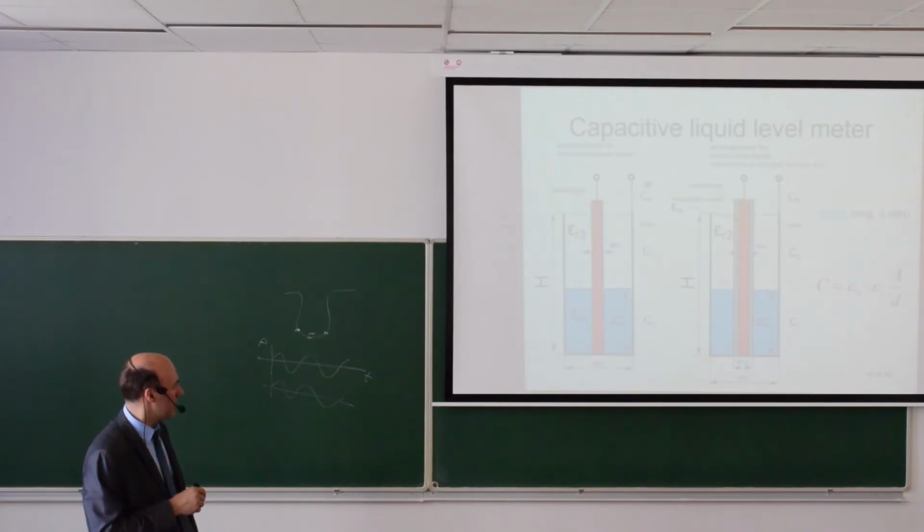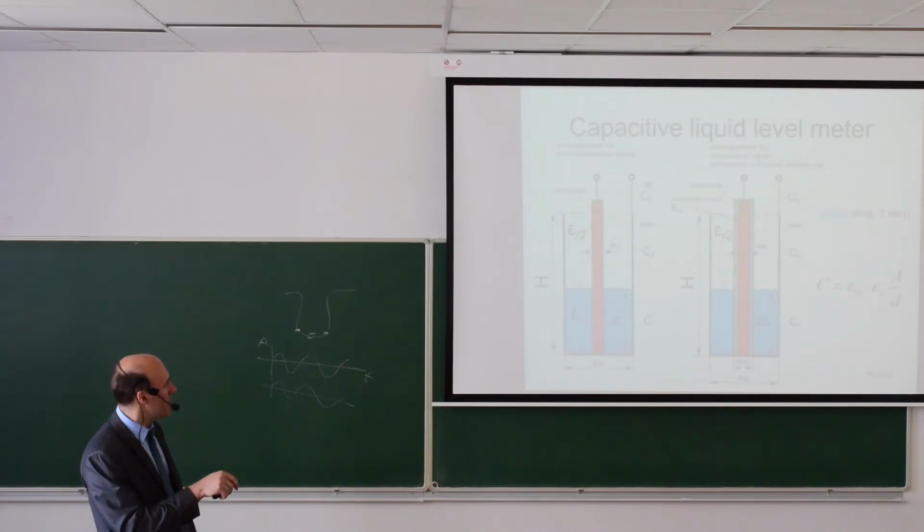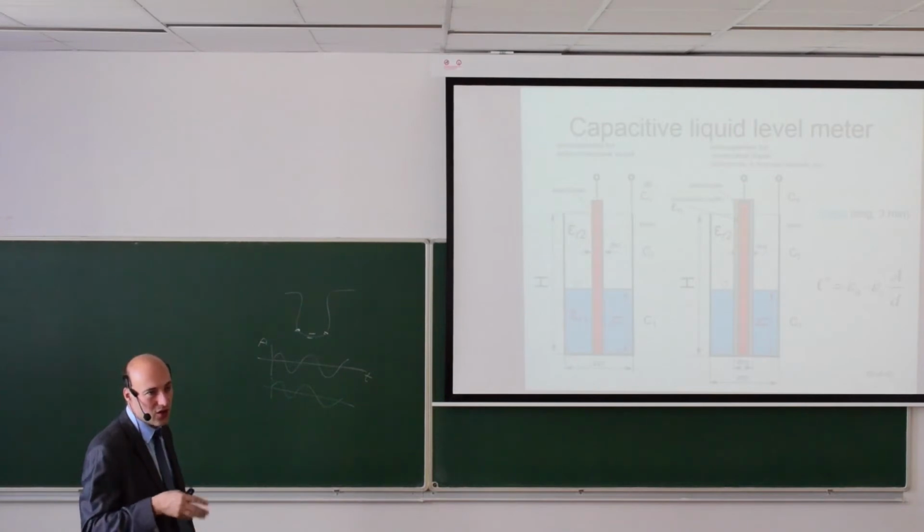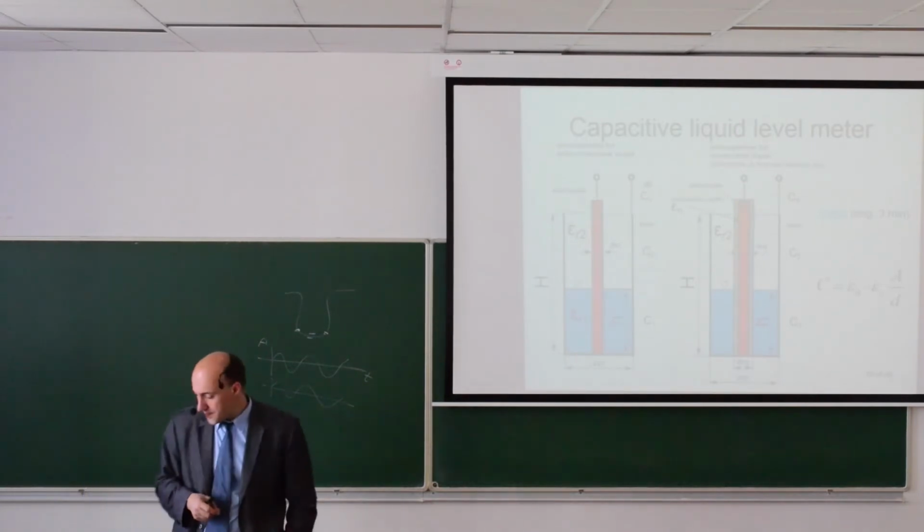Water is slightly conductive, so for water it's the best to use already an insulated version like this. So we have one electrode that is insulated and the other is not. So again, here the one electrode is the tank and the middle electrode is installed into the tank.